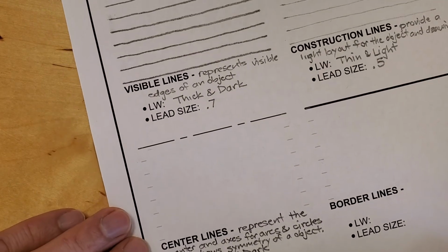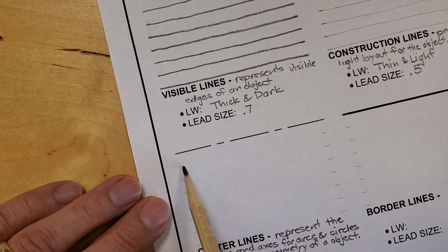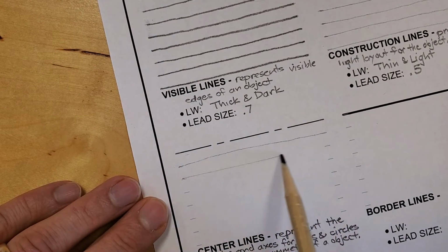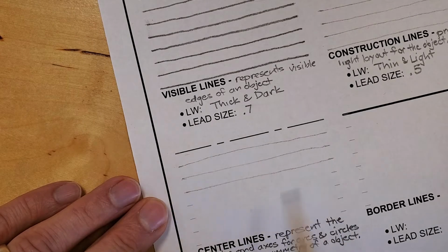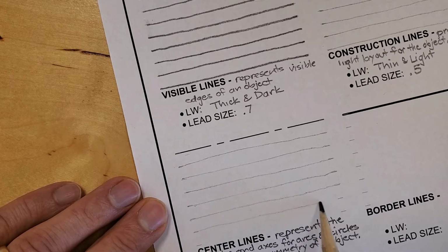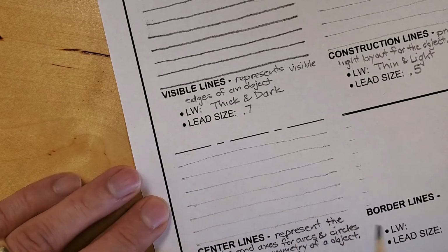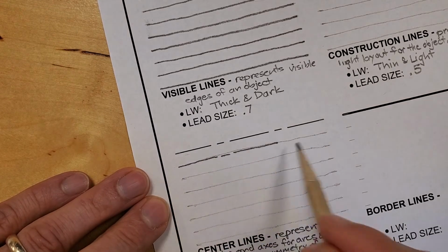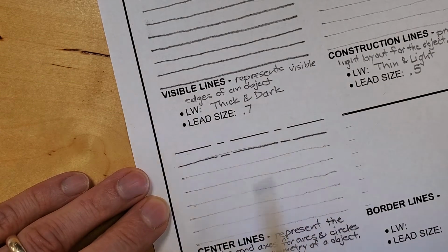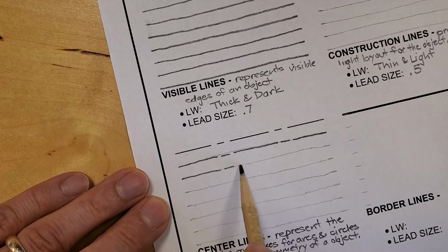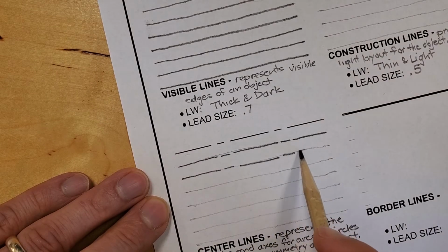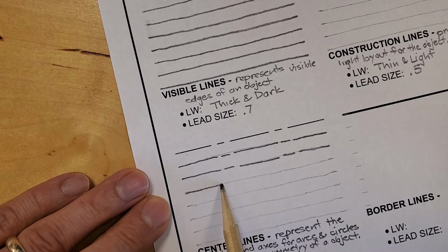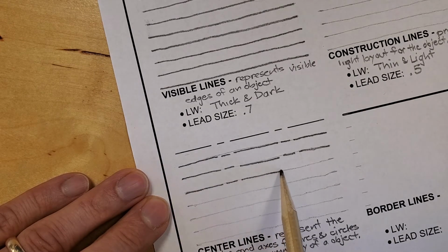All right, so again, like the hidden line, what we want to do is come across to here with some quick construction lines. That one's a bit skewed. So focus on the end point. Trust yourself that you can get the line there as straight as possible. And then go over that line. I'll kind of miss it a little bit. But go over that line with the symbol for a center line, which is a long line, dash, long line, dash, long line. Okay? It typically ends with the long lines. The dashes are in between.